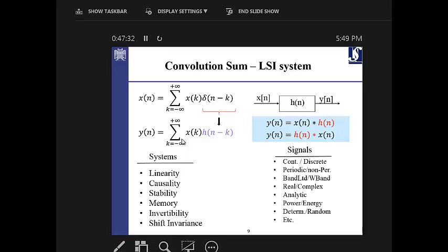So, we're showing everything in the convolution system, in the linear convolution case. So we see that x of n applied to the system, which is LSI, we get the impulse response, which is a convolution of these two things. And we have to know that convolution as a linear operator is also permutable. So you can easily permute the place of x of n and h of n.